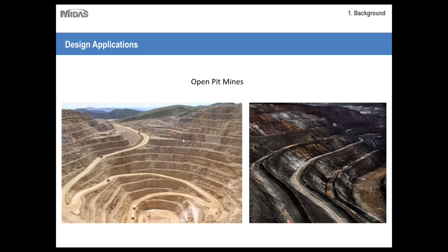Okay, then open pit mines. Open pit mines, or open cast mining, is a surface mining technique of extracting rock or minerals from the earth by removal from an open pit or burrow. As you can see, open pit mines are dug on benches, which describe the vertical levels of the hole. These benches are usually 4 to 60 meter intervals, and the size of the machinery being used will determine the length or the width of these intervals.